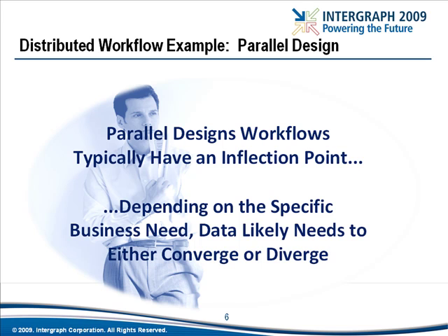In our example, some of the reactors may be running reactions containing chlorides. This moves the design away from stainless steel towards glass-lined equipment. This may be for the reactor only, or perhaps the reactor, the filters, and associated piping, or it could be for the entire reactor train. Whichever the case, the engineers on the project will decide at what point the design must diverge, and it is at that point that the 3D data representing the design will be affected as well.